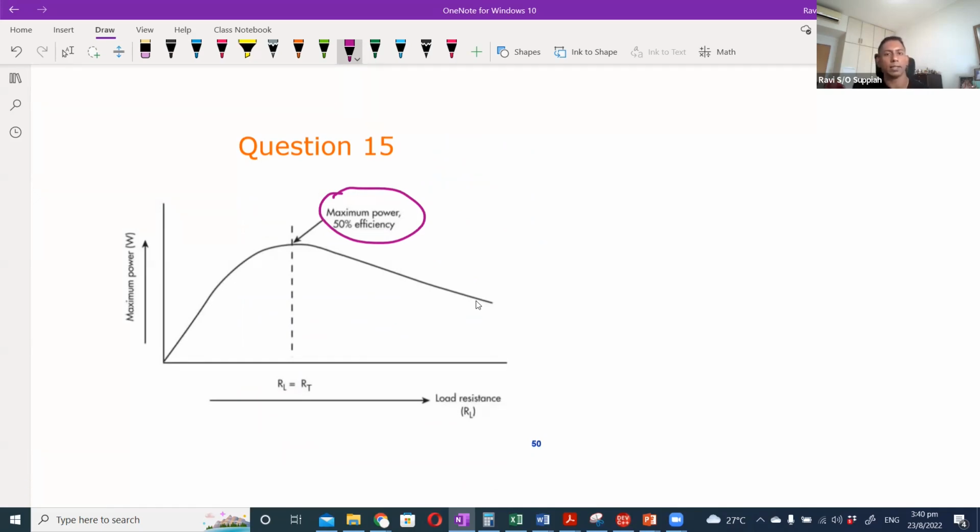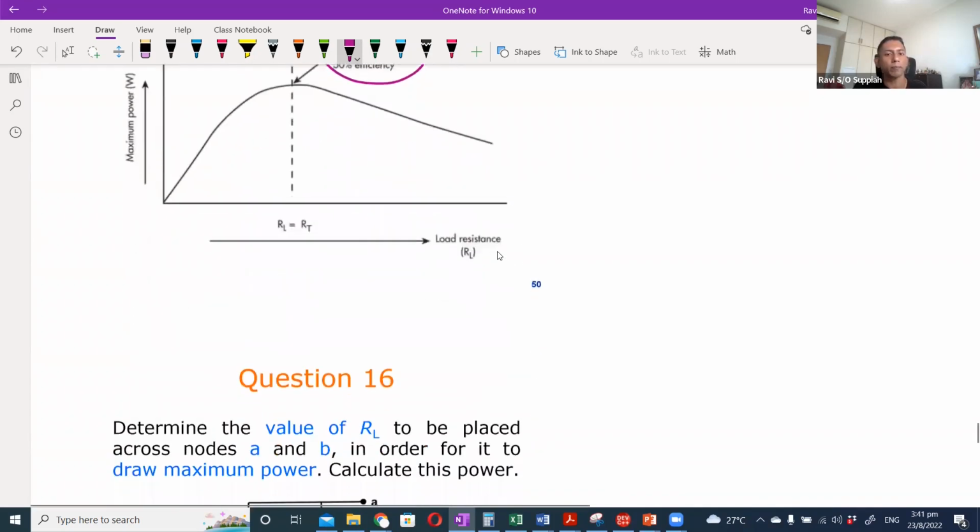Again, for now, maybe you will not see the effect of this so much yet. But when you build your own circuits, you may see that, how come the power delivered to the load is very low, my LED is not so bright, or the motor is not so fast, or something like that. Then you may need to come back to the Thevenin's equivalent to see whether the load resistance is matching the Thevenin's resistance. Then we can calculate to see whether something can be done.